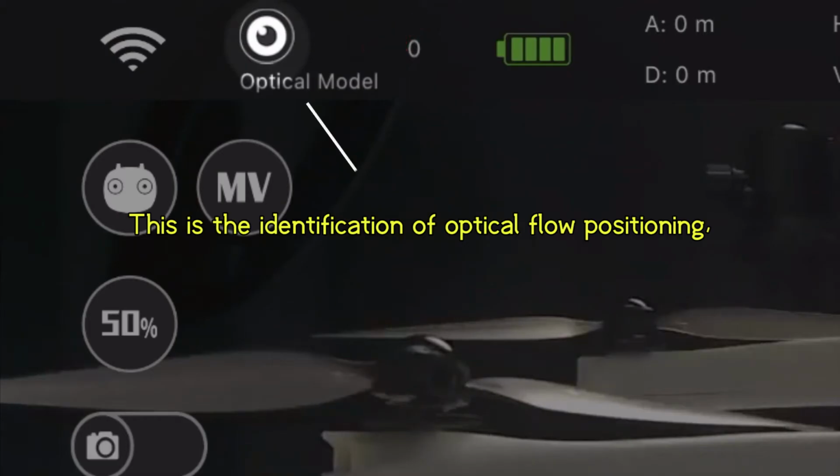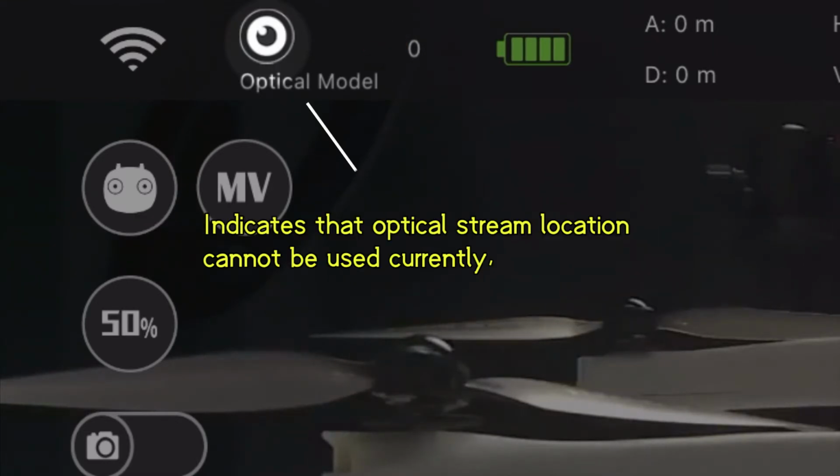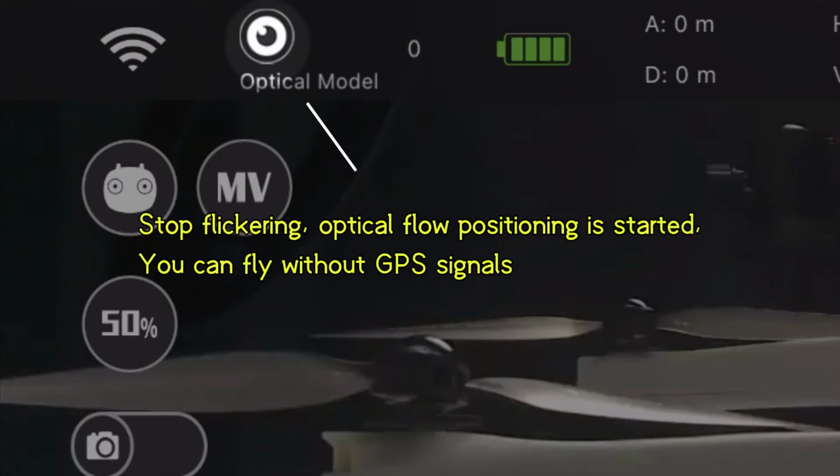This is the identification of optical flow positioning. When it flickers, it indicates that optical flow positioning cannot be used currently. When it stops flickering, optical flow positioning is started. You can fly without GPS signals.